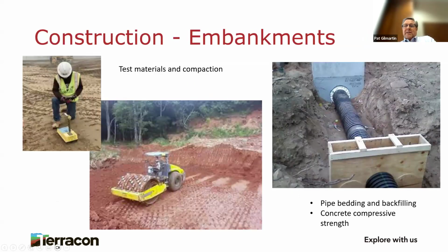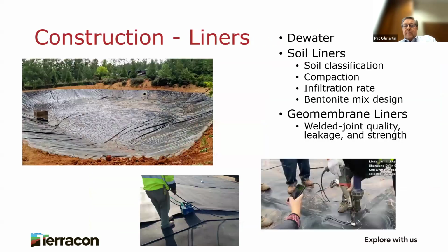Embankment materials need to be tested for classification, to make sure they're low permeability enough soil, and compaction is important, like on every earthwork job that we do. Outfall pipe installation, including any cradles, anti-seep collars, seepage diaphragms, need to be observed. Photograph, please. If concrete anti-seep collars or cradles are used, we often will do concrete compressive strength testing just to make sure that the material supplied is good. Sometimes we do. Not that big a deal. It's not a heavy structure. But I've been asked to do compressive strength testing on concrete cutoff walls or cutoff collars before.